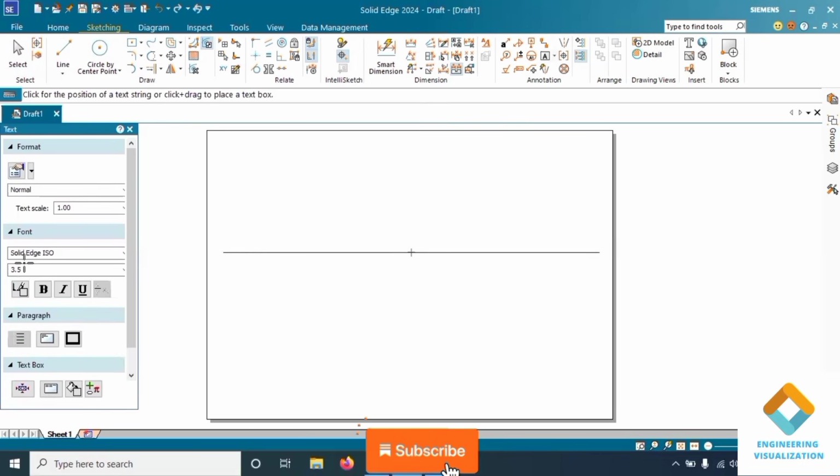So first we'll be drawing an XY line and writing VP and HP. Here the first position will be a circle, but for that circle they have not given any dimensions. They have mentioned the dimensions for the ellipse, that is major axis 60 mm and minor axis 40 mm. So the major axis of the ellipse will be the same dimension as that of the circle.